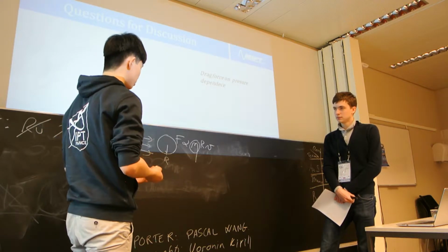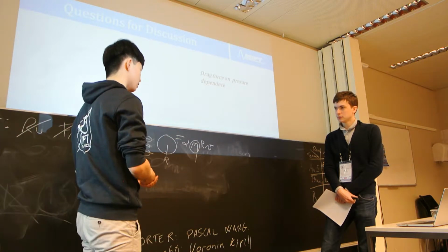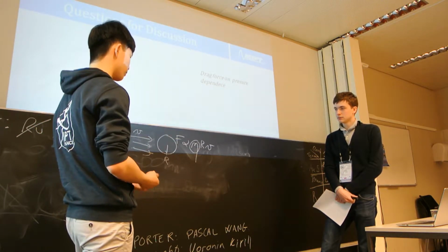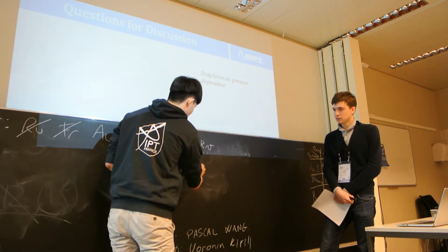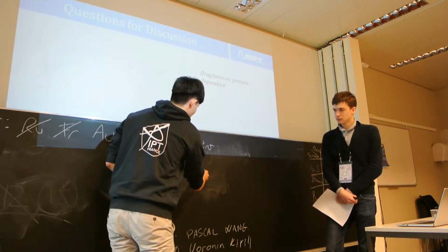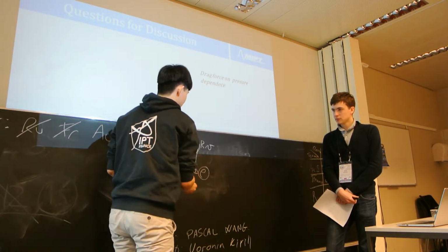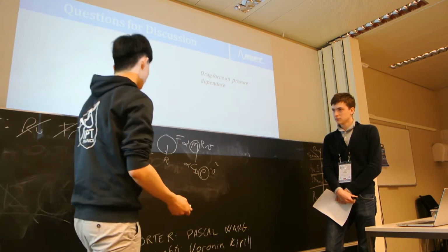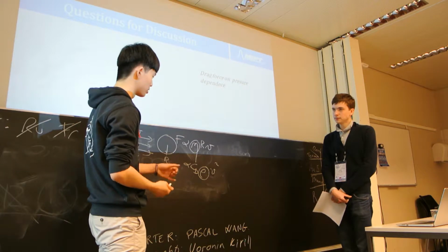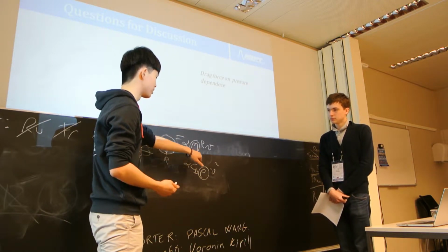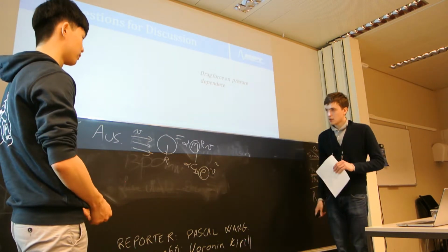So when you change the pressure, you change the properties of the fluid, for example in this case the viscosity, so it changes the linear drag force. And when the Reynolds number is higher, it's proportional to this time the density of the fluid, which is reduced also when we lower the pressure. So when you diminish the pressure, you modify the properties of the fluid, either viscosity or both at the same time, and this changes the drag force.